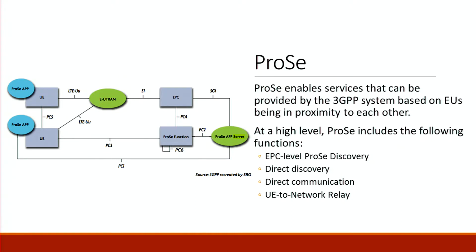This is all in the Evolved Packet Core, or EPC. And we already know that the EPC is connected to the EUTRAN, the Evolved UMTS Terrestrial Radio Access Network. That is, in the EUTRAN, you have the eNode B and the terminals. And then we also have the UE, the terminals. So these 4 blocks here are the same as you already know.